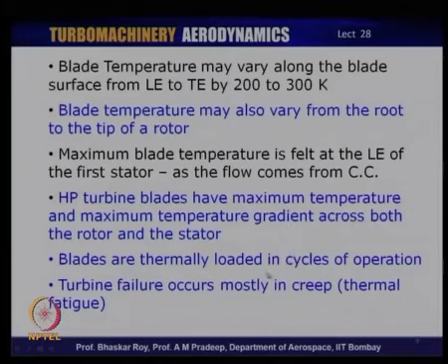So, the failure of the gas turbine often occurs in creep, which is the thermal fatigue kind of compounded stress that occurs, mainly due to the thermal fatigue. The compressor blades, for example, do not fail in creep, they fail mainly in loads during operation. Those blades of course are much thinner. The turbine blades are much thicker, as you have seen, but the thermal load indeed creates a lot of problems. So, even though turbine blades are thicker and made of high temperature material, even then the life of a turbine blade is often much less than that of a typical compressor blade.